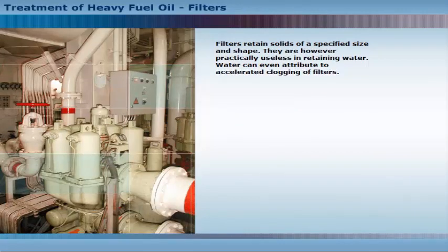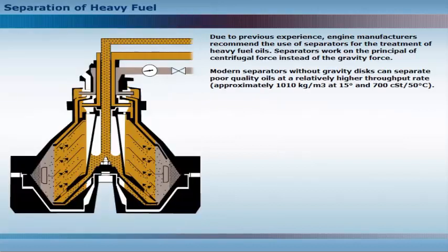Filters retain solids of a specified size and shape. They are, however, practically useless in retaining water. Water can even contribute to accelerated clogging of filters. Due to previous experience, engine manufacturers recommend the use of separators for the treatment of heavy fuel oils.